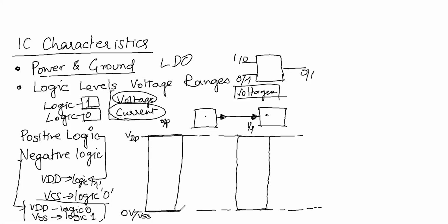Typically, it is a range, which, let's say I'm exaggerating, but still I am drawing two values. So this is the output level. This is known as VOH minimum. Output voltage when logic is high, what is the minimum value for it?